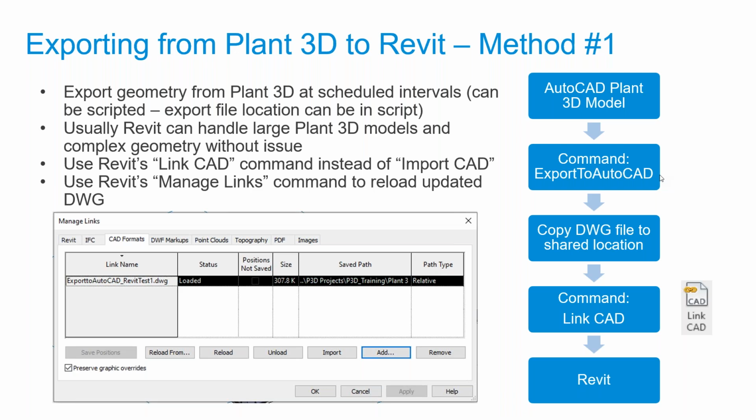The second method, which we'll come to in a moment, requires more work and allows Plant 3D objects to be included in section views and other features inside Revit, which then act more like Revit native objects. This method has the drawback of needing to be redone or reinserted when the Plant 3D model changes. And the choice ultimately depends on your preferences and your project preferences between the ease of use of the drawings and having complete functionality inside Revit.